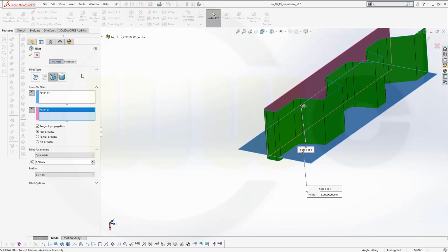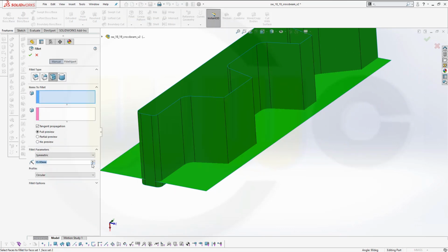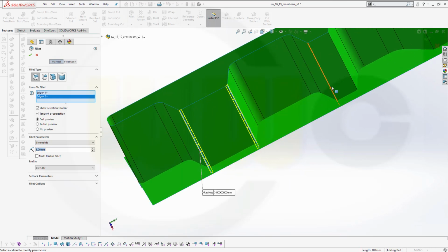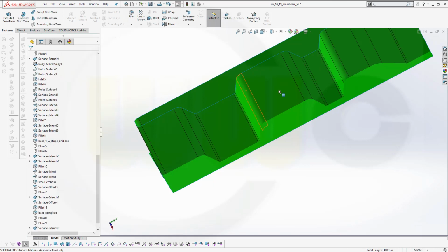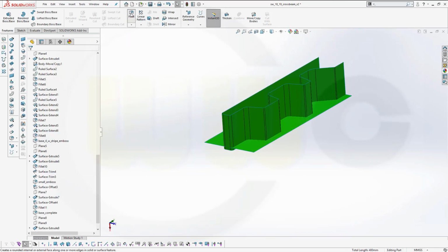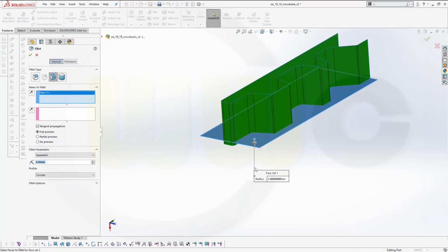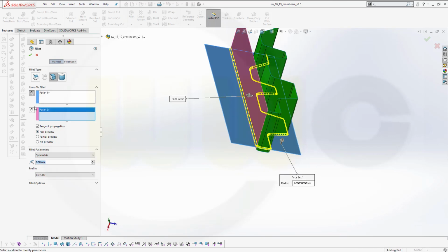So I forgot, of course, to make fillets here. So go for fillet, 3 millimeter or 2 millimeter, doesn't really matter, but go for edge fillet. This edge, that one, this one, that one, and this one over here. Confirm. Now I should be able to do a face fillet, 3 millimeter, 2 millimeters between this one, go up, and that one to the inside, and confirm.